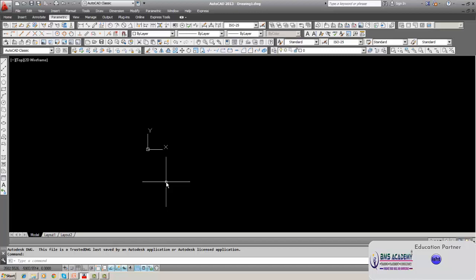Normally we can see in a 2D drawing only two faces if it is a projection drawing. If you can see the three faces, then it becomes an isometric drawing. The object will have totally 6 faces. So by looking at the 3 faces, you will be able to understand to some extent the component, or you can visualize the component, how it is, before starting to produce the component or any other thing from raw material. Now I will first create an isometric plane.